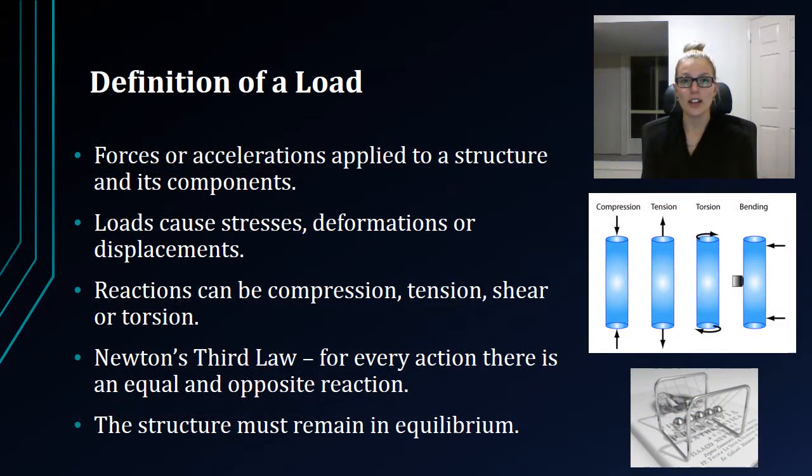A load is defined as a force or acceleration that is applied to a structure and its components, which in turn can cause stresses, deformations, and displacements within the structure. These reactions can be in the form of compression, tension, shear, or torsion forces. For the structure to remain stable and safe, it needs to be constantly in equilibrium, where the forces in all directions are equal to zero. Newton's third law is also relevant in the design of structures, where for every action there is an equal and opposite reaction.